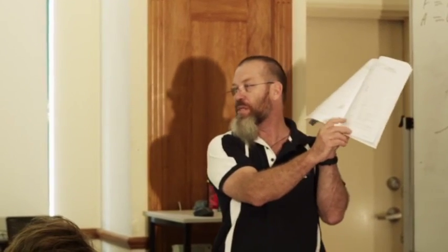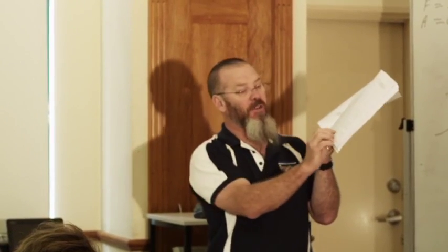I'm looking at type G here on the bottom of the page, which is ply bracing. If your nails are 50 millimetres apart, it gives you 16.7 kilonewtons of uplift. They're big numbers. But if you space the nail centres out to 150, it reduces that uplift down to 10.4. So this is what some of your bracing systems are about, the ability to hold the nail for a start, but putting the nails close together increases the capacity of the bracing systems. Therefore, it also affects your tie down. Okay? So that's those ones there.